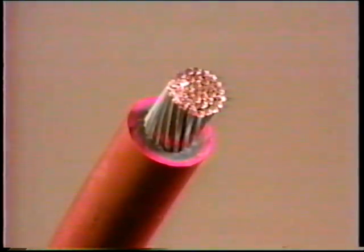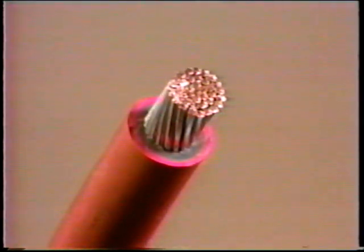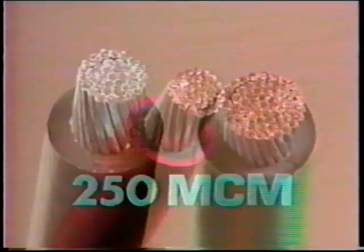A circular mil is a circle that has a diameter of 1 mil, or 1/1000th of an inch. In this case, the area is equal in size to 250,000 circles, each having a diameter of 1 mil. So this is a 250,000 circular mil conductor, or as it's usually abbreviated, 250 MCM. MCM stands for 1,000 circular mils.